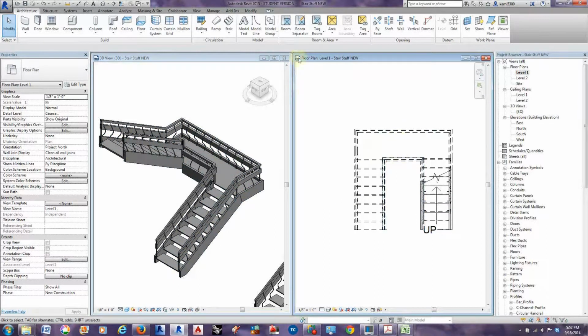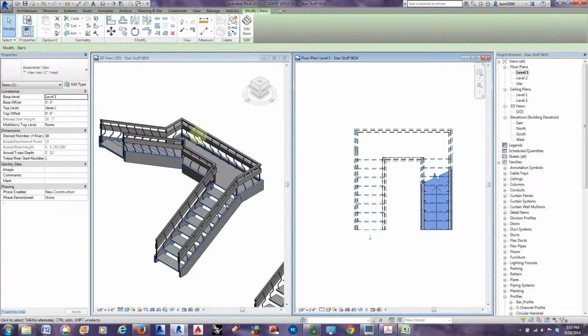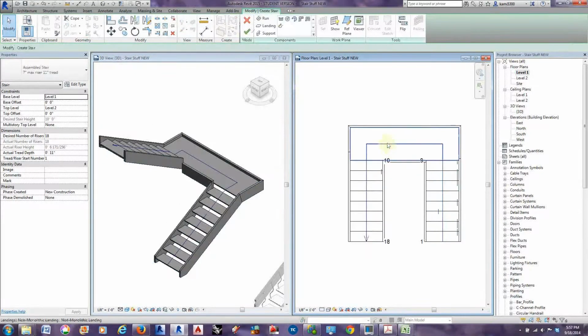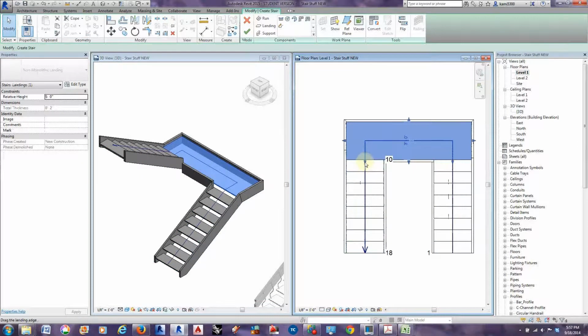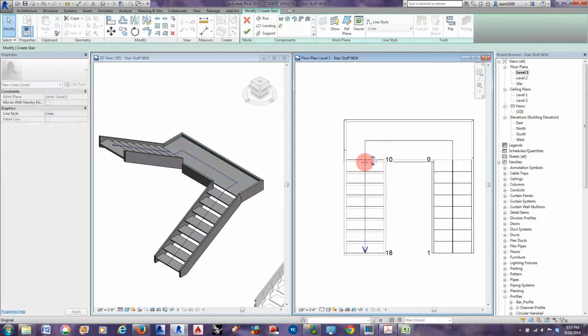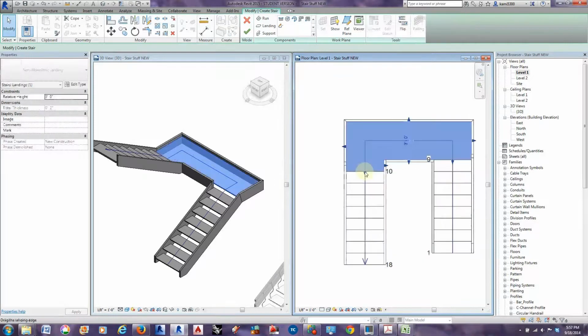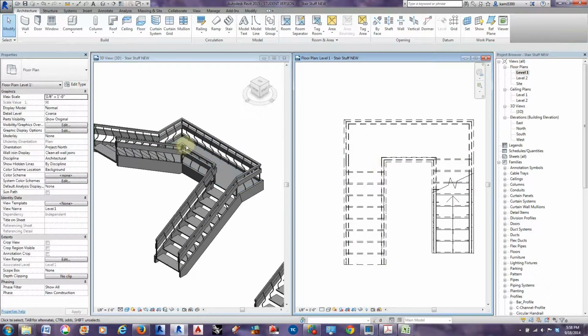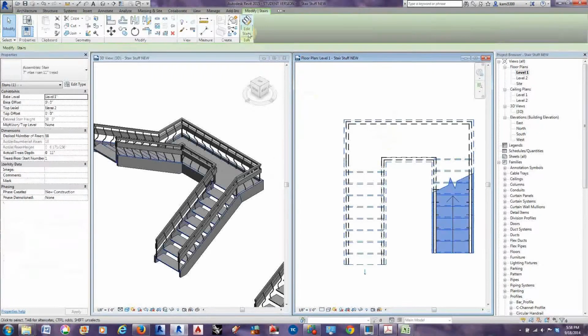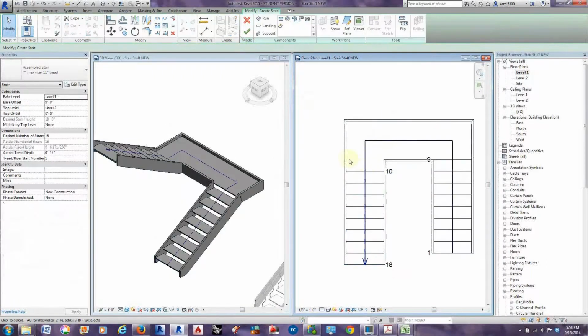At any rate, you can start to adjust how that sits by editing the stair and changing your landing. So for instance, if we selected our landing and pulled this arrow, we can adjust the steps to start having a little space here before we start rising again, so that when we finish the model, it starts to look normal, and you don't end up with these disjointed railings.